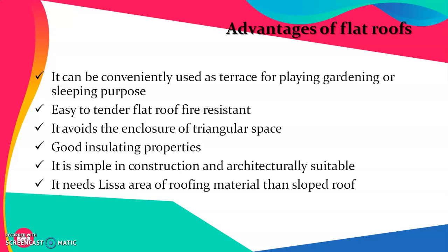The different advantages claimed by the flat roof include that it can be conveniently used as terrace for playing, gardening or sleeping purpose, which is not possible in case of sloped roof. It is easy to construct, and fire resistant. It avoids the enclosure of triangular space, which is very common in case of sloped roof.